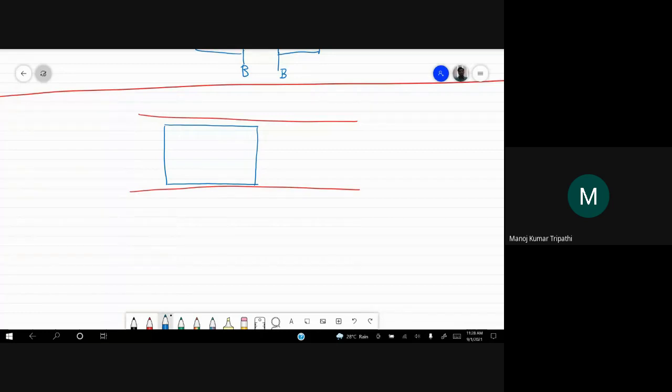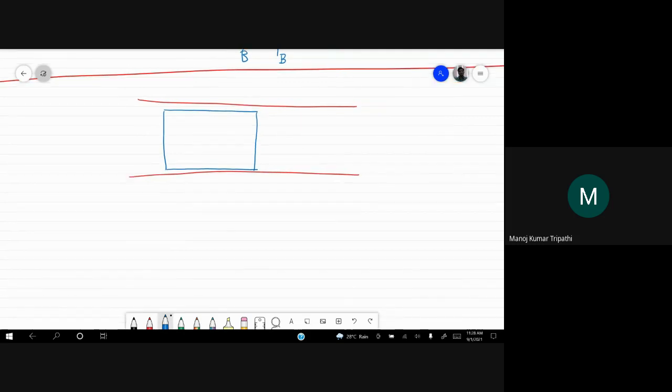Yeah. So what we'll do now is we'll consider a fixed volume in space. We are not going to track a fixed mass of fluid as it moves through this pipe. We are going to consider a fixed volume, which I have marked by this blue box. And we will observe the fluid that is coming into this volume and the fluid that is leaving this volume.